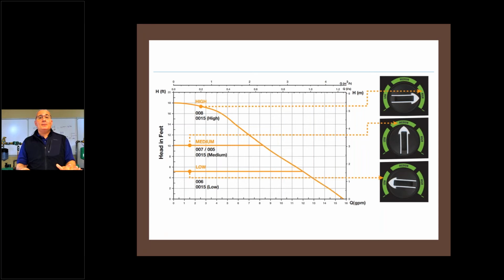Well, we could discuss this many ways, but in reality, most of the heating season, we're only at 40% capacity. So there's a very good chance we could run at 5 feet of head. If not, you can bump it up to medium, and I can handle 6 feet. But what would happen is if we did bump it up to medium, so let's remember, I need 52,320, so I need 5.2. So 5 would be my mark here for GPM. At 6 feet of head, I'd be up here. But we have this thing called a system curve, which would start down here and work its way up this way. All right, because that's the design of that particular install. That is the system curve that will happen.